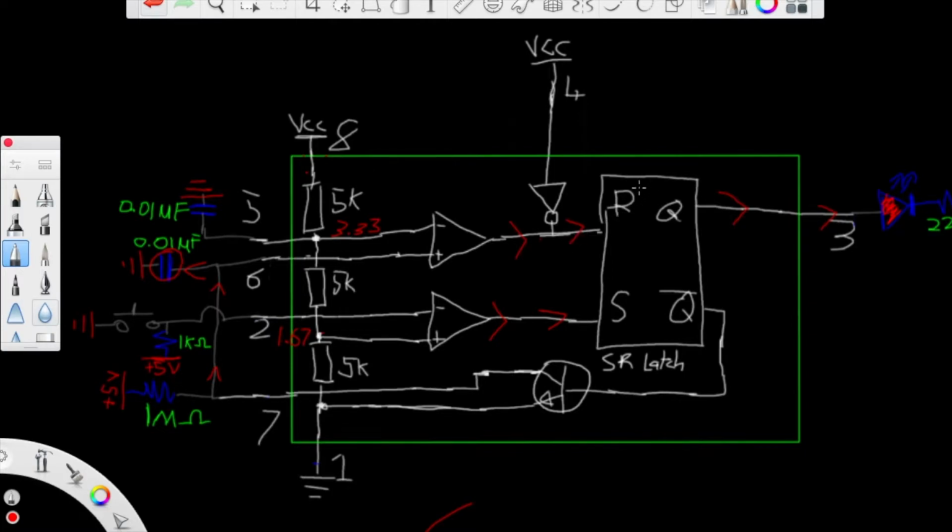Now that's going to reset the latch. So assuming you've taken your finger off the button now, there's going to be no current flowing through here. It's going to reset the latch. Not going to have current flowing here. These LEDs are going to turn off, and this not Q is going to go high. You're going to see it's pulling 5 volts from pin 7 here like it was before,